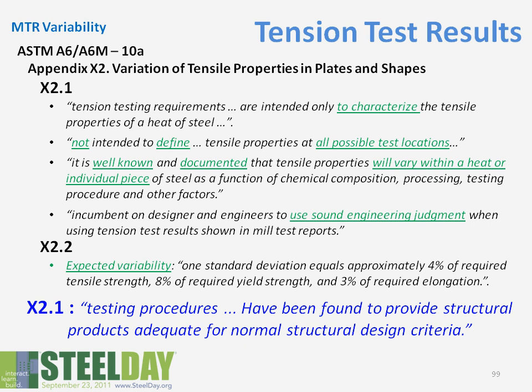What about physical properties? Well, there's a very little referred to but very important appendix in ASTM A6 that deals with the variation of tensile properties in plates and shapes. It says that the tension test requirements are intended only to characterize the properties. They're not to define the properties at all possible locations.